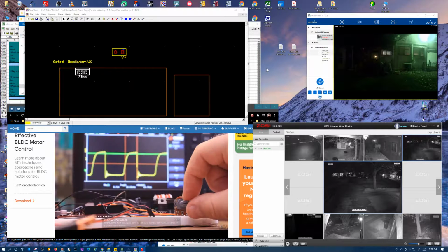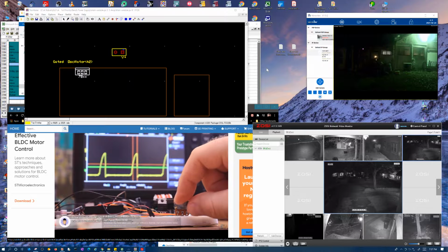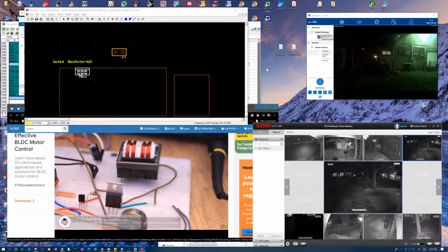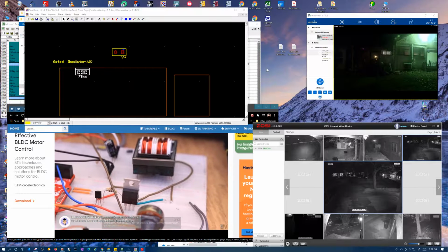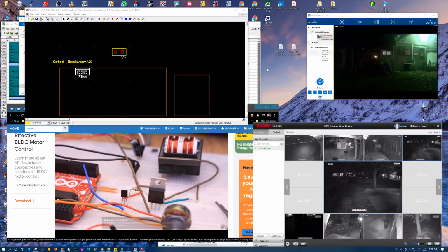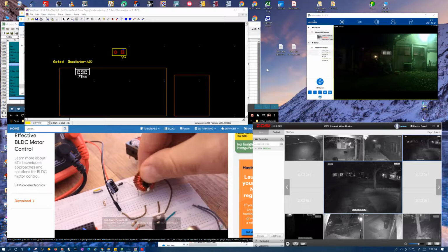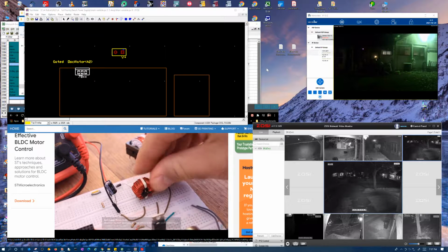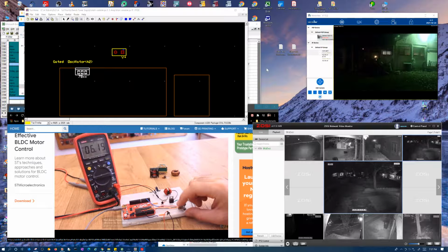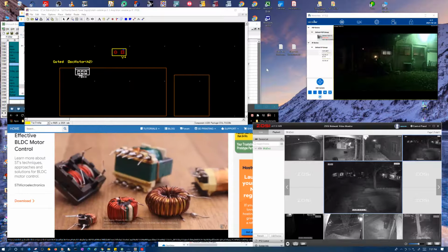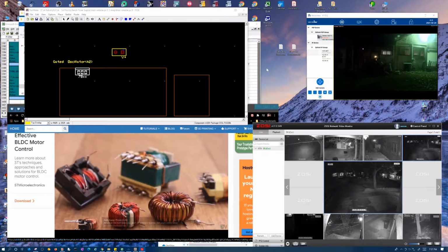But instead of the potentiometer, we could add a simple feedback, connected to the Arduino analog input, and set the voltage at a defined value, let's say 5 volts. And also the used coupled inductor doesn't have to be this big. A small one would do the job as well. As you can see, with this other one, we can still regulate the output. They could come in all sorts of shapes and sizes.